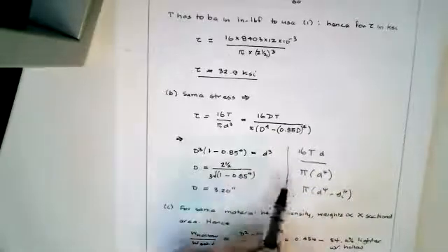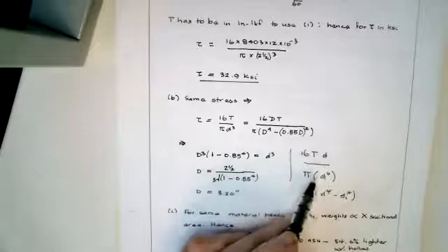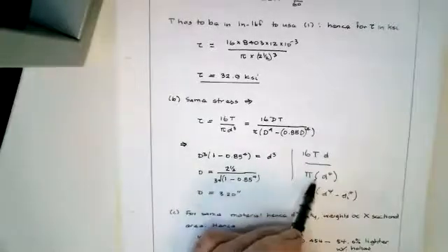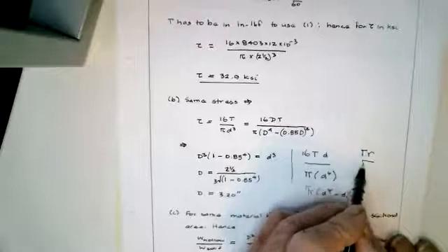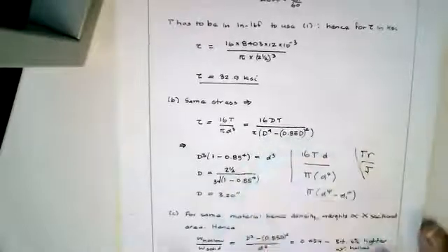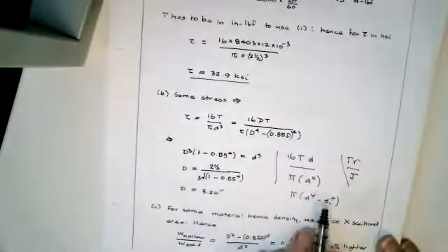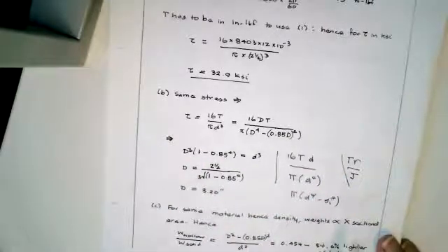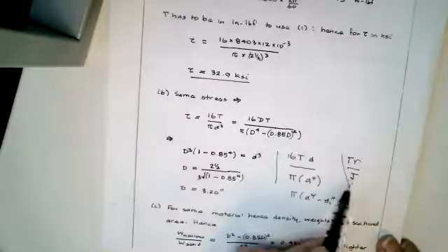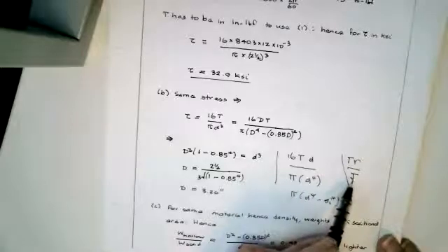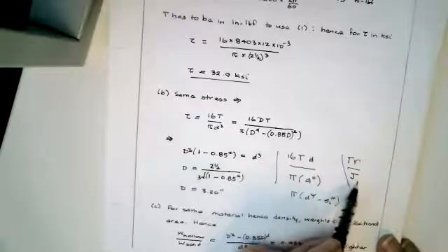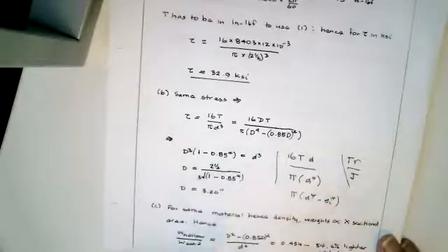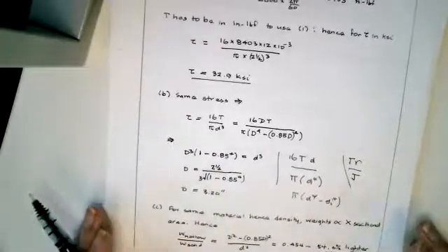Sorry, it's TR upon J, which is the formula for the shear stress at the outside of a shaft. And so if you go look up J, you get pi upon 32 d to the fourth when it's solid, but you get a different J when it's hollow, and that's where that comes from. Okay, but you need to go look that up.